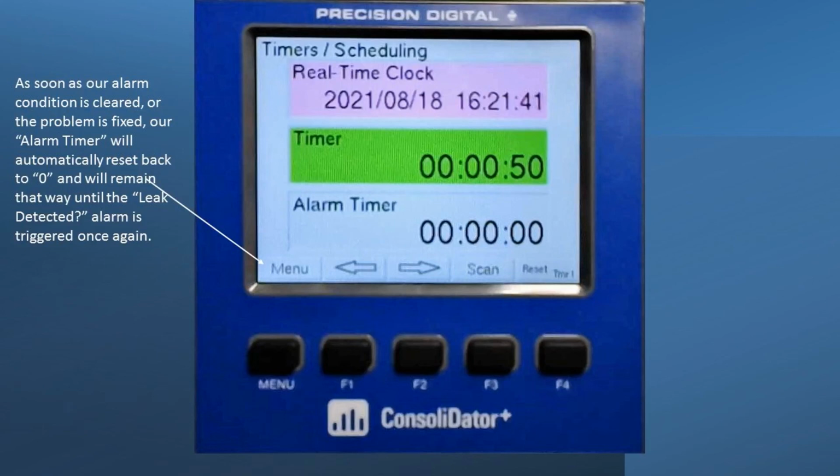Someone also asked, can I trigger the timer via digital input? And the answer is yes. As I had mentioned before, the timers can be triggered based on practically anything. They can be based on a digital input, so a physical feedback from an operator. They can be triggered on time of day.